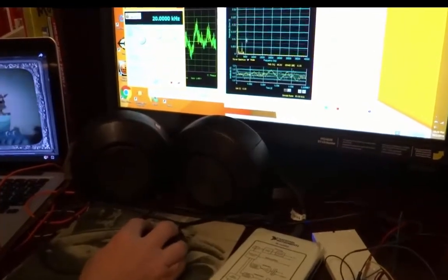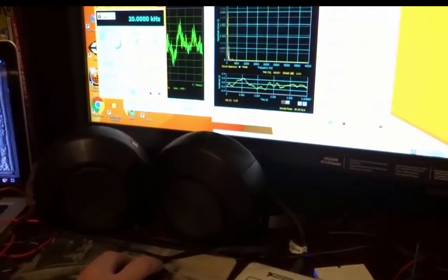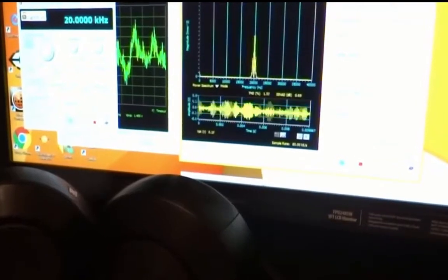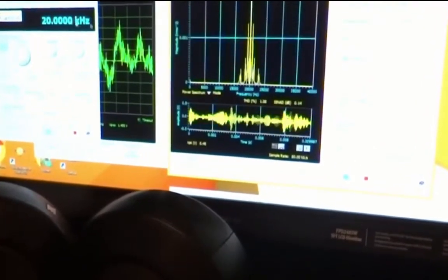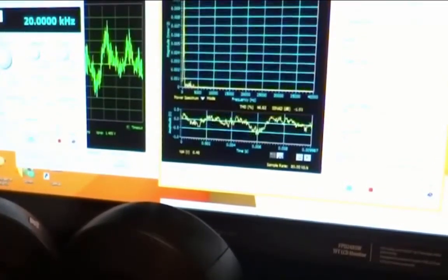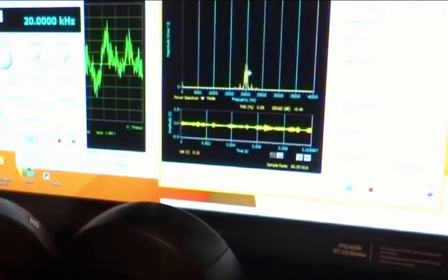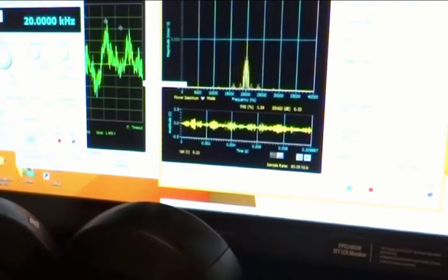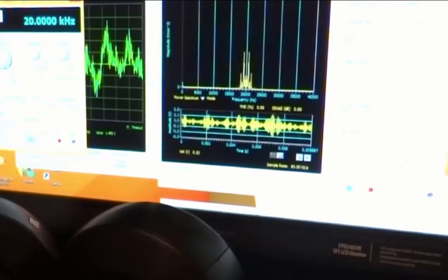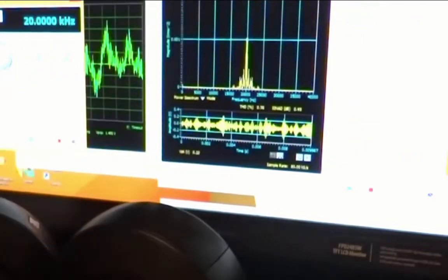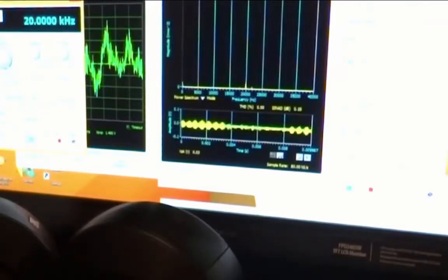So right now we're looking at the actual input to the modulation process. Let me switch this to look at analog input 1, which is set to the output of the modulator. So we see what happens here is the frequencies that started much closer to DC have now been shifted to live up here at 20 kilohertz, according to what you get if you multiply a signal by a sinusoid of some frequency. I can look at the effects here. If I take this 20 kilohertz and start shrinking it, you'll see two effects. You'll see this move to the left, and you also start to hear a little bit more of a distorted version of the signal.